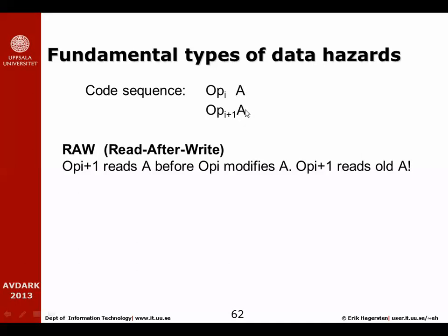and the following instruction is a read instruction. So that was the example of data hazards we saw in the previous example, where we did a load into register, and that register was read in the very next cycle. So that's called the read after write hazard.